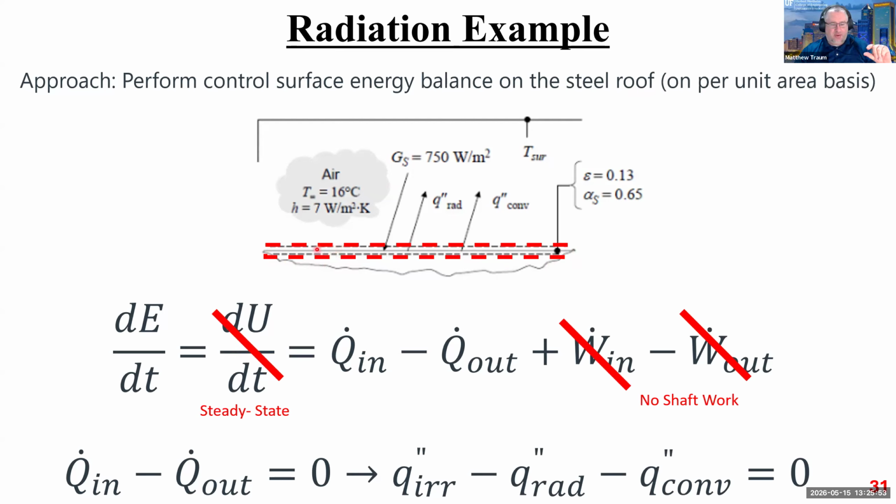It's very, very thin, so I don't have any mass in there, but it does experience all of the energy fluxes, and I'm going to use it to account for all of them, do my first law energy balance, and then set all those energy fluxes equal to each other, swap in my temperature equations for my energy equations, and then solve for temperature. So same approach we've done before. This one's just radiation.